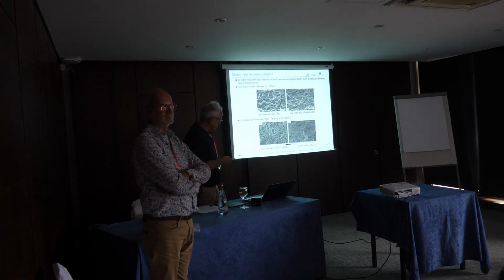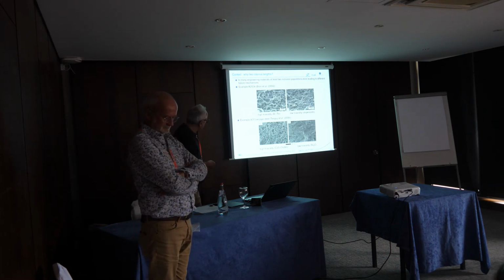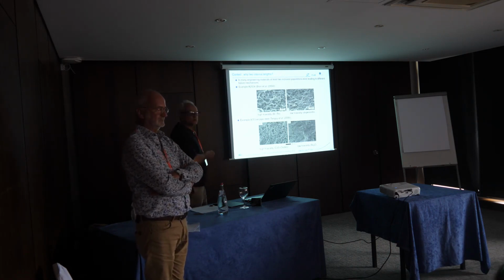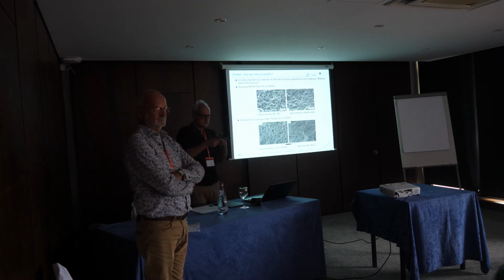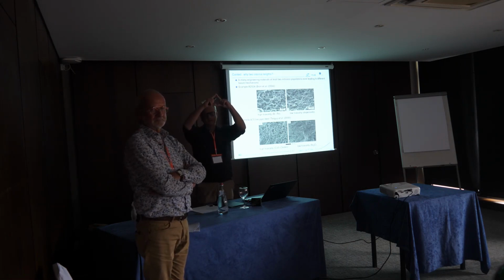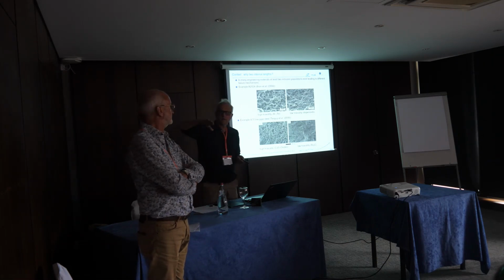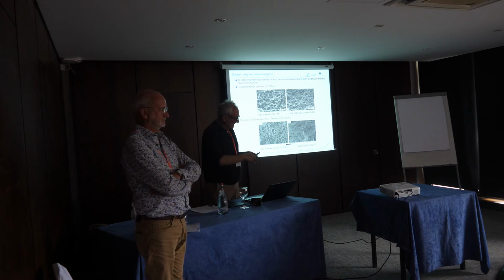We go back to the aluminium case. In the aluminium case, this picture is a fracture of a sheet. This picture is taken close to the initiation of the ductile crack, where we have the triangular crack initiation zone. And this picture here is taken where the crack is propagating slant. Triaxiality drops, and you get that.